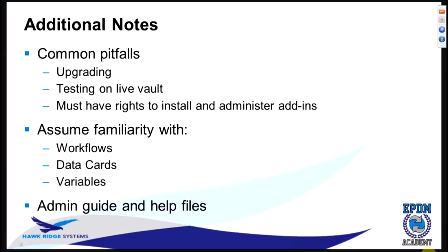A few additional notes before we jump in: some common pitfalls that you will see when you make dispatch scripts. One common pitfall is the upgrade process. Typically, upgrading dispatch is not a big deal, but sometimes you can run into the instance where, because dispatch does not upgrade when you upgrade to a new service pack or new version of SOLIDWORKS, that means maybe something in the code has changed between 2013 and 2014 or 14 and 15.